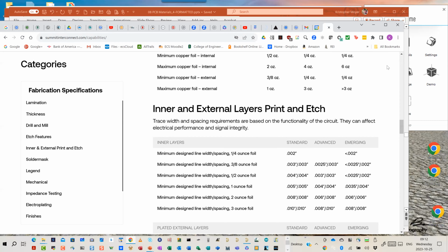If you say, I need some exotic material in my board, that's going to be a cost adder versus if you're using generic materials that they have in stock, no cost adders. So those are several of them, right? So all these manufacturing process steps that we're going to talk about next week, if you stay within the standard capability, no real adder. The big cost adders are going to be things like this, where I push into advanced or emerging technology capabilities at the fabricators.